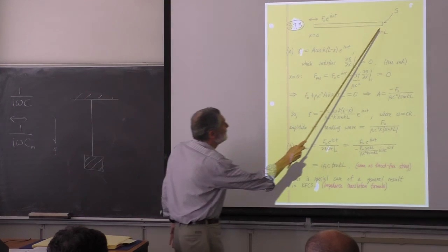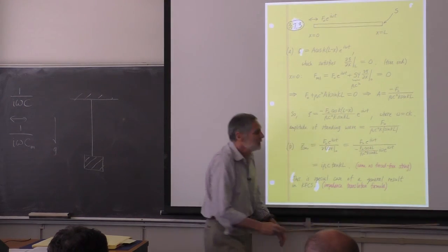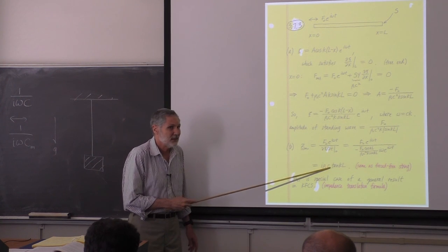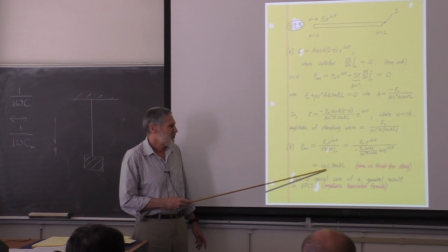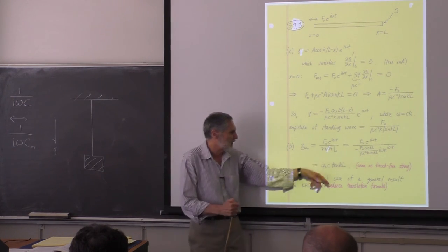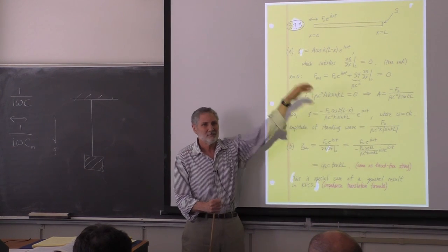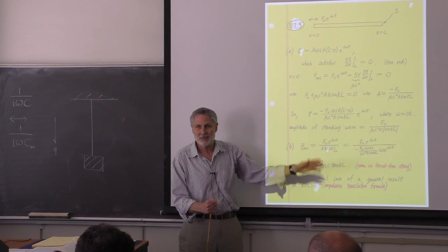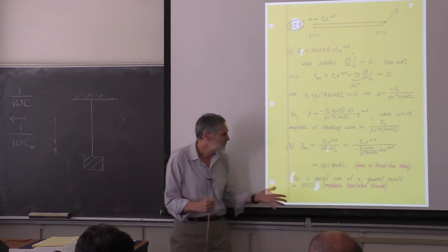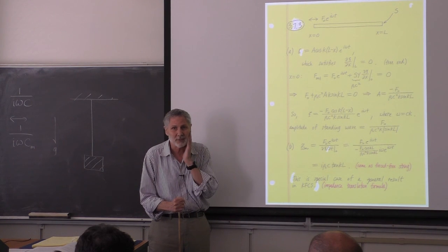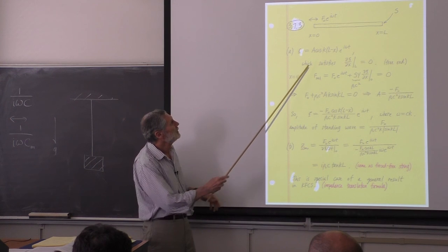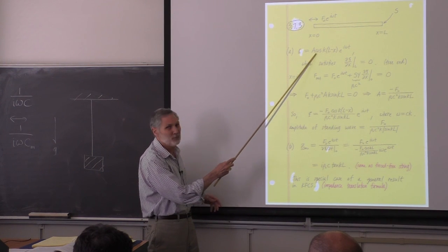Let's now imagine that this is infinite. And I want to know, what's the input impedance? Do I just let L go to infinity here? You can see that's going to be trouble, right? Because as L goes on, this just keeps oscillating between 0 and infinity. The branches of the tangent function just continue. So what's the mistake? How do we get out of this problem? What's the assumption in here? Way back here, how did we get this?